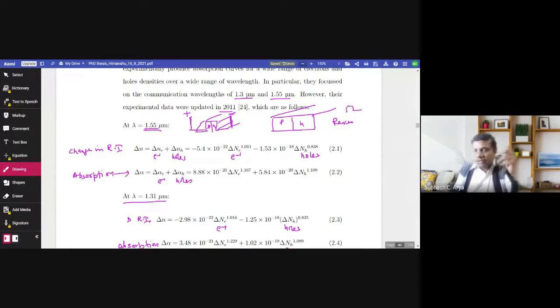This applied potential, which works as a bias, is now your information signal. It will be sometimes on, sometimes off. In this way the depletion width will vary according to the modulating signal. In this depletion width area, there are charge carriers like electrons and holes. Holes are the majority carrier in p type and electrons are the majority carrier in n type. So there is a change in the actual concentration of electrons and holes.